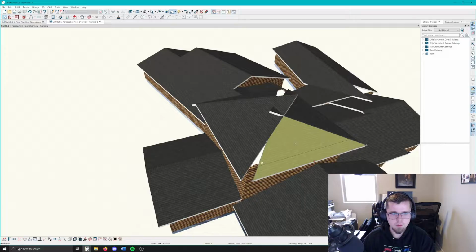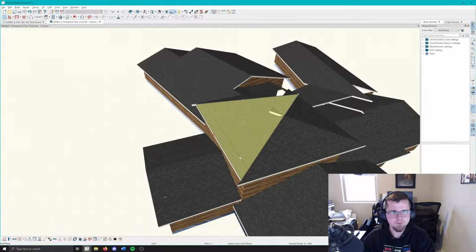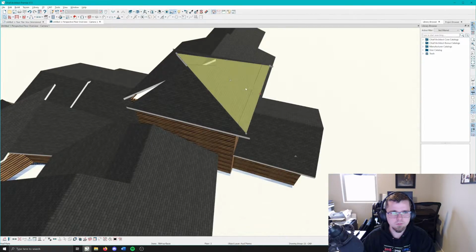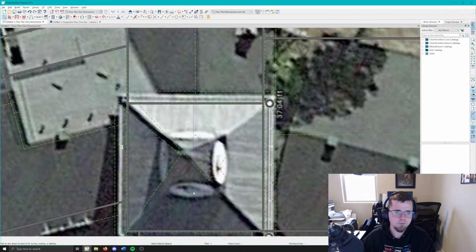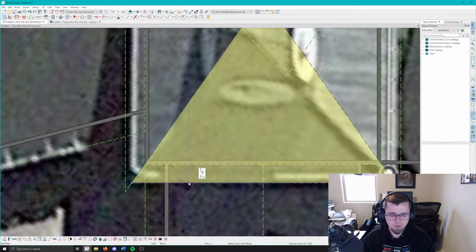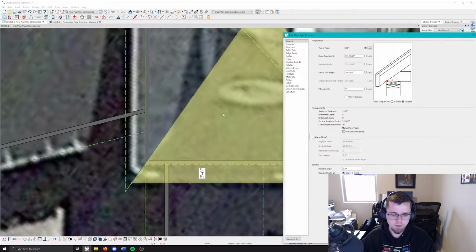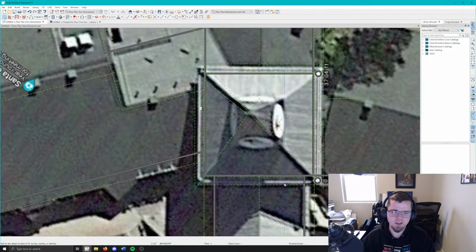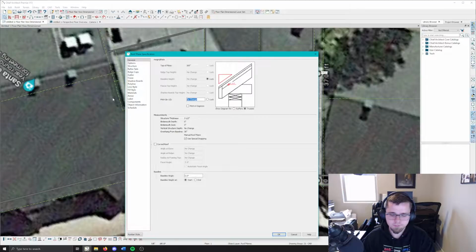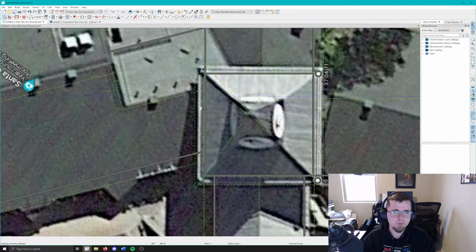So a number of these got sort of messed up here. Oh boy. I'm not sure what happened to these. The ceiling height on them, or their plate height where they're resting, I think either that changed or I didn't get them all to a 6/12. I think that's the problem. I didn't set these all to 6/12, just that one side. I have no idea if that's going to help. Let's take a look real quick though.